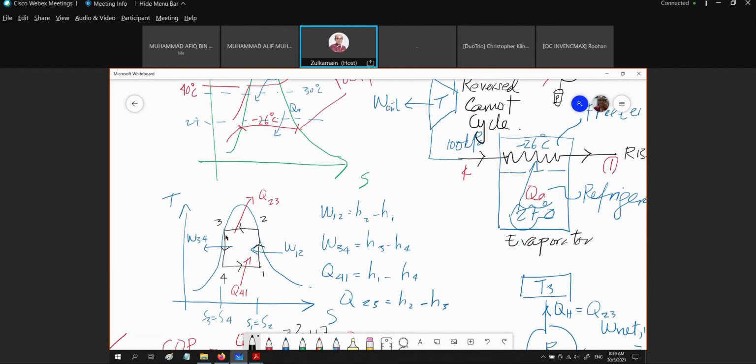Okay, from 1000 to 100, that is the main purpose. But for a device such as a turbine, which is costly, the amount of work we are going to have is very small, because state 3 is a saturated liquid and the source of energy is very small. Then we are going to have W34 very small. So compared with the turbine, which is costly, what we need is just a device which can have the expansion effect so that we could go from high pressure to low pressure.